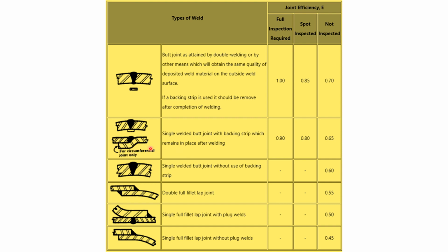There's a special machine which is called a joggle machine. In the manufacturing industry, if you ask what a joggle machine is, the plate edge is bent like this. What happens? One shell, the adjacent shell, goes inside, so that here you do a weld. Okay, this is also called type 2 welding, and only for circumferential joints.